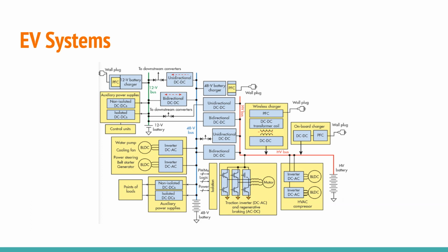These converters must be able to withstand heat and vibrational stress from road conditions while handling high power and current. Again, silicon carbide MOSFETs improve the efficiency of traction systems because of their operation in higher switching frequencies and lower switching losses. They also reduce the size of filters and the need for heat sinks, thus making the vehicle lighter and better on mileage.